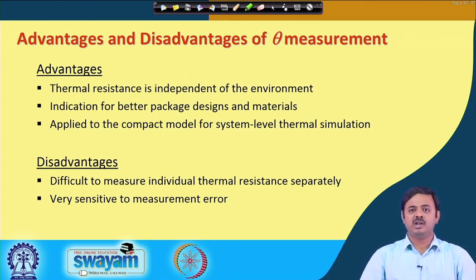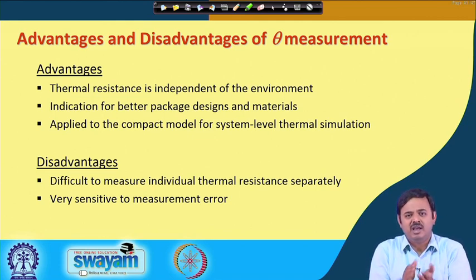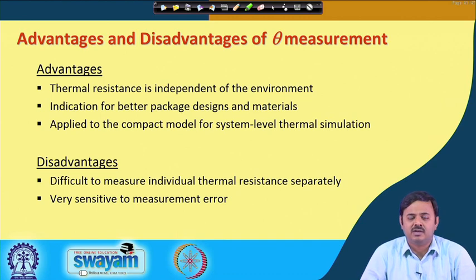I am doing a modeling of the entire motherboard with all these components. Are we going to model every layer of the interface material, every heat sink? No, we would just put this package at the place and define a thermal resistance in both directions, towards the ambient and to the board.